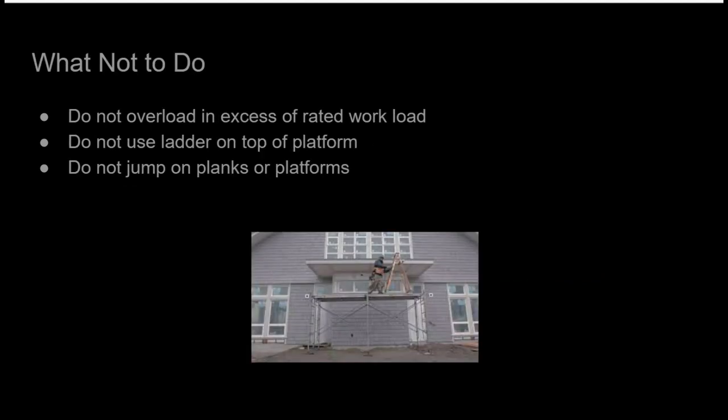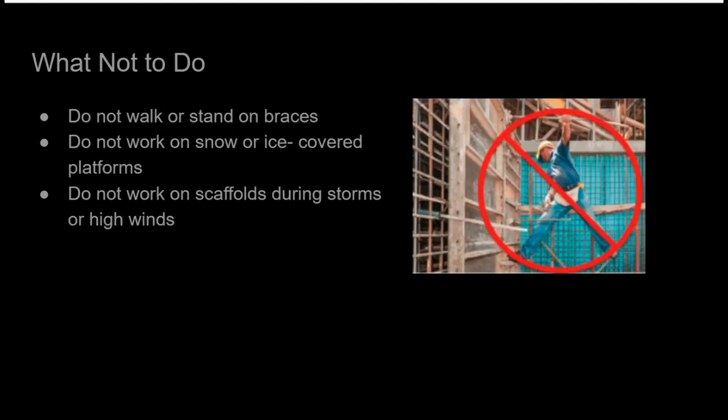Know the rated workload and never load in excess of it. Don't use a ladder, bucket, or other contrivance to reach up higher, and don't jump on planks or platforms. Do not walk or stand on braces. Don't work on snow or ice-covered platforms, and don't work on scaffold during storms or high winds.